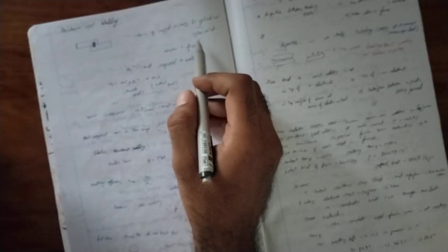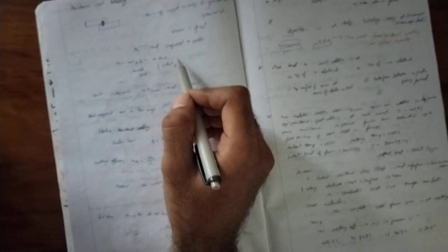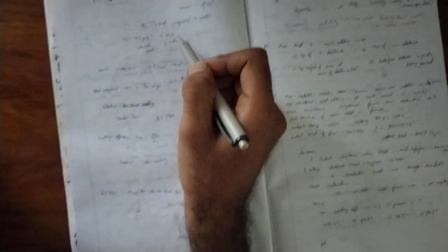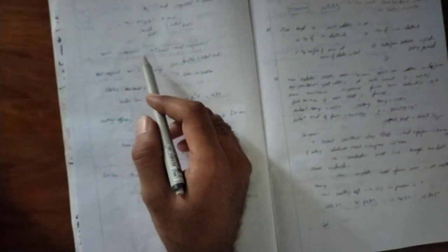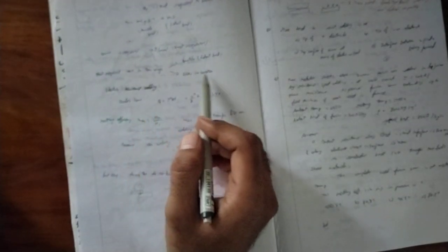In resistance spot welding, you can see this is the volume of the weld nugget. It may be cylindrical or spherical, so we need the volume. Next, the heat required to melt is m c_p delta T plus lambda, the latent heat. So the sensible as well as the latent heat is required. Next, for 1 millimeter cube, how much heat is required? That is very important. The heat required or transferred covers sensible as well as latent heat, as given in the question.